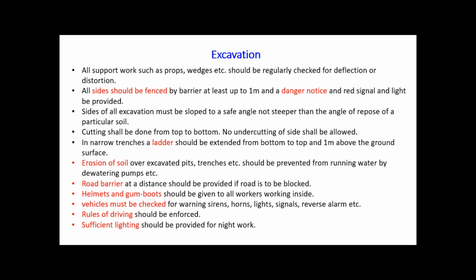So all support work such as props, wedges, etc. should be regularly checked for deflection or distortion. All sides should be fenced by barrier because this excavation activity is going on. Then other than the expert persons or the persons who are allowed for this activity, other persons are not allowed in that area to avoid the danger. So we have to display some danger notices also in that area.